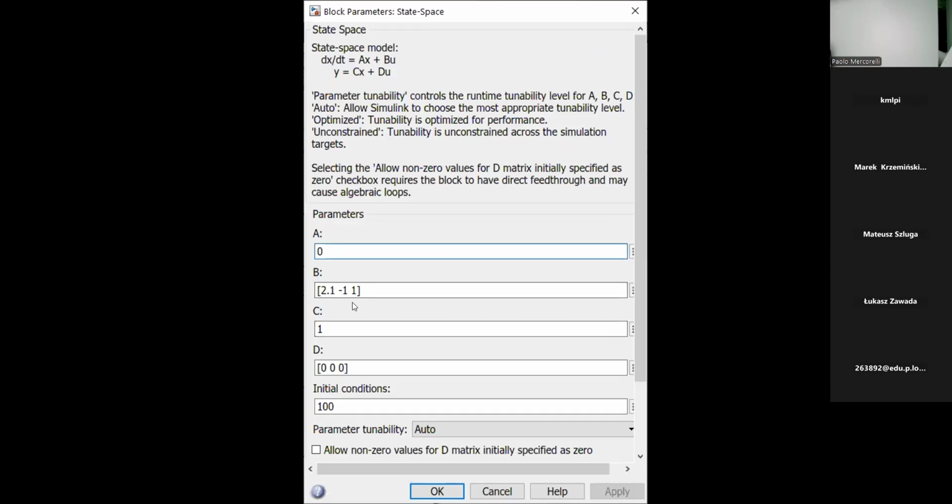Because we don't have a linear part. B, we can see that it consists of 3 elements. 2 comma 1 is exactly a little bit the concept to realize the wrong cancellation, no? Because we thought that the coefficient was 2. In our model, the coefficient was 2, but really in the real system it is 2 comma 1. But the control is so robust, if beta is large enough, it overcomes the error in terms of cancellation, no?